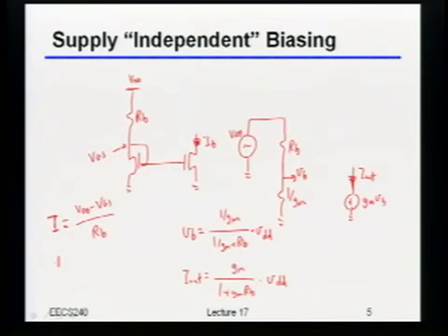Kind of makes sense, right? Because if I make the RB really big relative to that GM, the voltage here becomes basically constant. And so the current over there should also be nearly constant. Okay, now, as we've already sort of hinted at, this sort of works, but it's really not great, right? Because what you really wanted was actually somehow that VDD minus VGS would be constant, right?